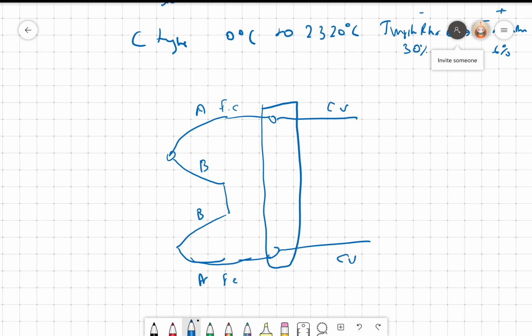When I put this again, there is a junction here, so there will be a voltage developed depending upon the junction temperature. But the nice thing is, if the temperature of this block is constant, I will have plus minus developed here.